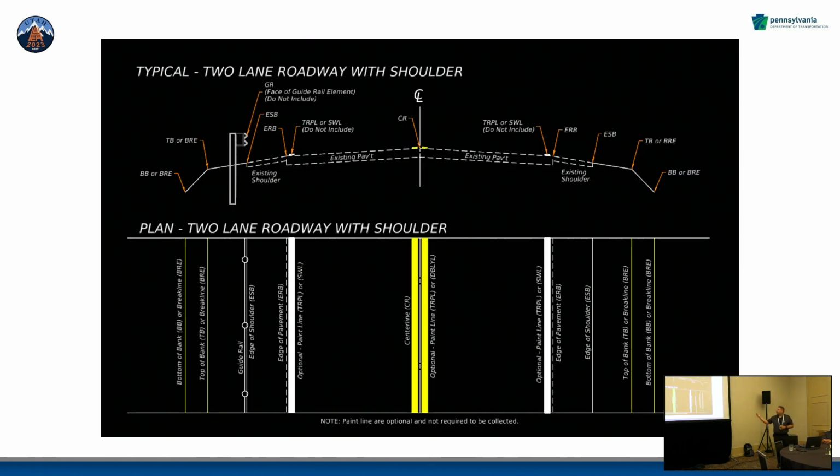And again, this is just something we're using to show some of this stuff. Even with point cloud data, if somebody tries to put line work to it, I don't want a paint line. I want the actual break. If I'm modeling, I'm probably going to try to use that break as a reference. Or if I'm checking slopes on existing projects, I need it in the right place. You can't have a good digital model without good data. So you need to really investigate your surveys and make sure your organization is looking at it.